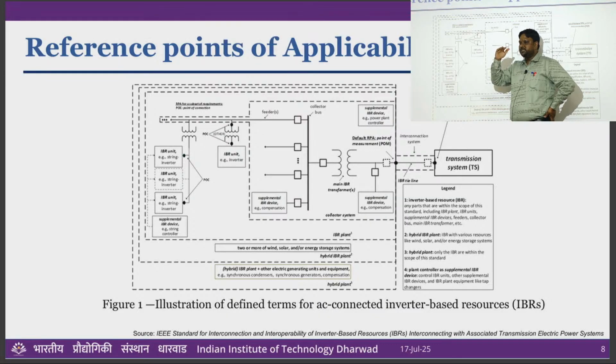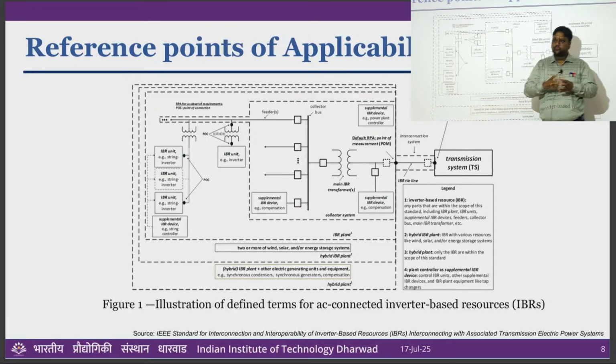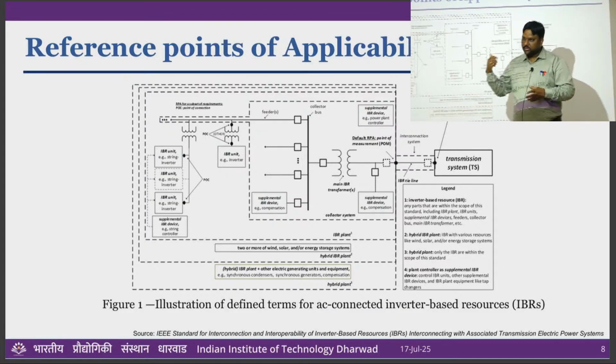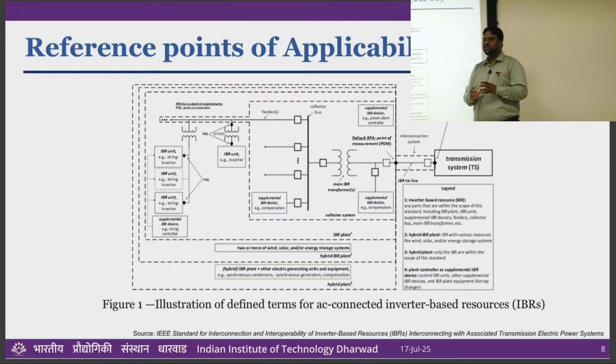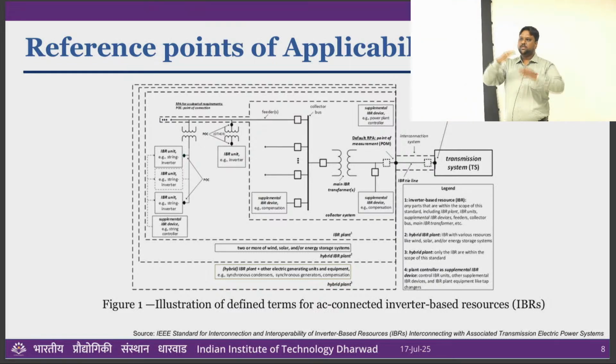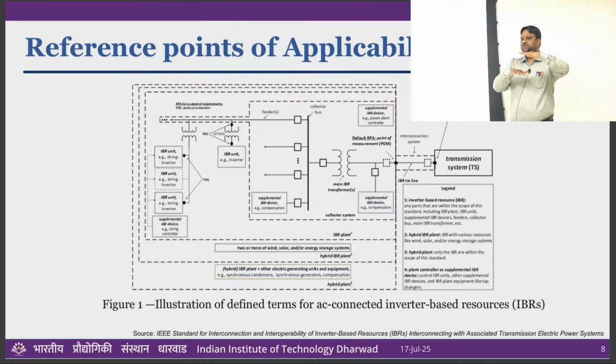So that has to be steady state. It will give you some time. Within that time, the reference will change. Then once the reference changes, your controller should follow that reference, following these dynamics. Your rise time should be this much, settling time should be this much, overshoot should be this much, and your band of operation should be this much.